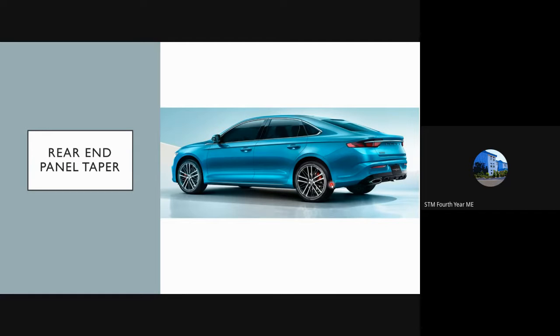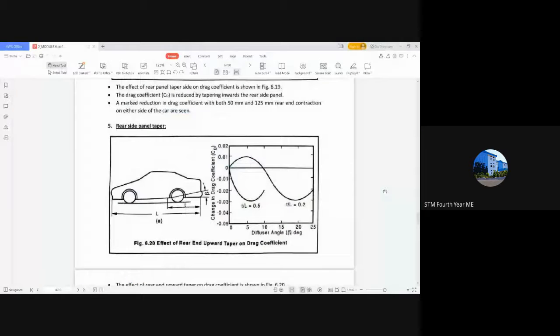And for that purpose we are increasing the area here, and while increasing it, the velocity here decreases, and the pressure here also decreases, and a region of high pressure will be created above the vehicle, and hence it provides a negative lift, and that is how it affects the lift. While in the case of drag, you can see here, it is the angle that is provided by the chassis and the taper.